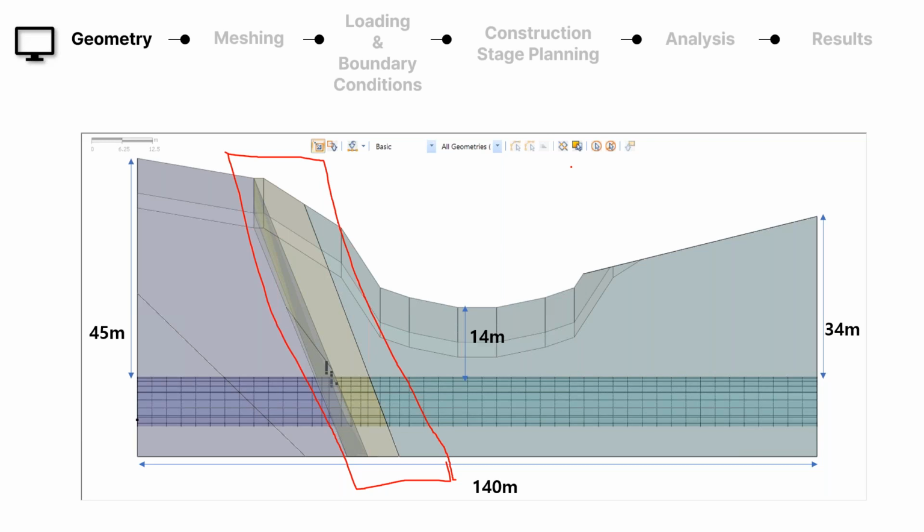So if we take a calculated guess based on our knowledge, or let's say engineering judgment, if we are approaching the shear zone, let's say from this direction or even from this direction, we have to ensure that before reaching the shear zone, the area near the shear zone needs to be reinforced. By reinforcement, it means some extra reinforcement is needed as compared to, let's say, these areas or this area. So this is what I have done in this particular model, and we will check around.